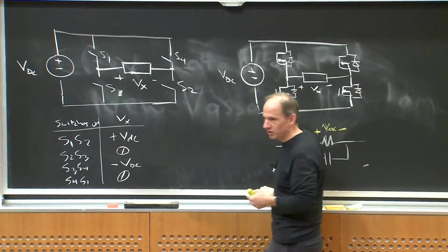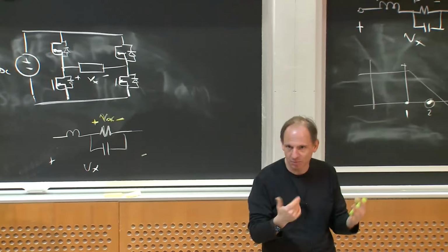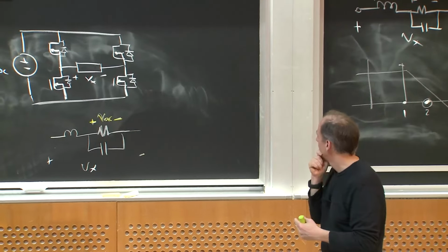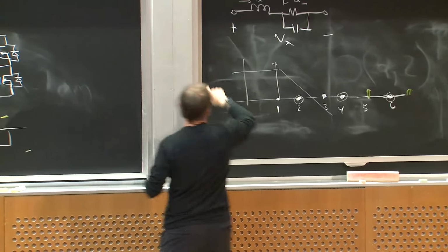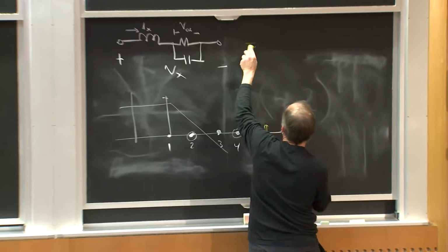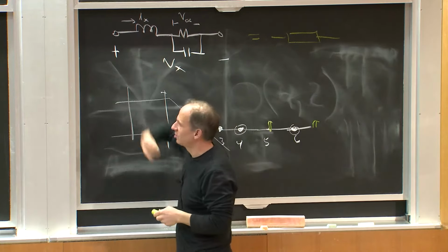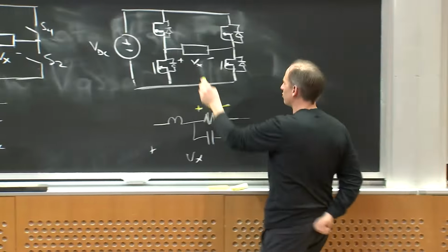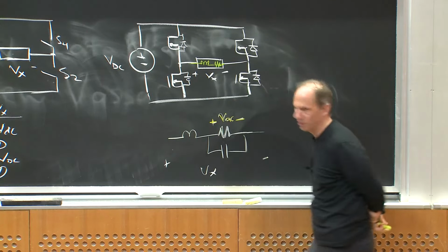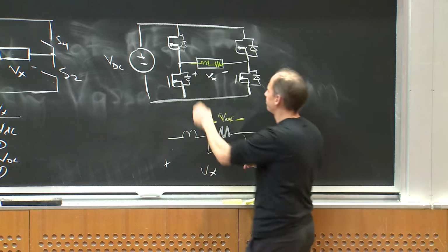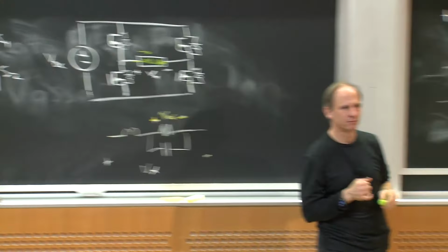One thing relates to how I control these switches in the real world. I mention this because there's theoretically controlling the switches and then there's the practical considerations. Suppose I put this kind of filter in here, equal to this box that I'm drawing. So basically, I've got an inductive load. If this load is somewhat inductive, or maybe it's resistive, this is what a motor winding might look like, right? I've got to be careful never to open circuit that winding.